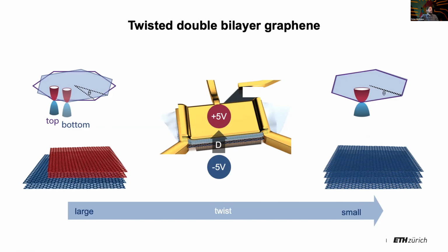I get delta R2 for the outer one, which is here. And then I can see whether the total resistance here, if I tune one to spin up and the other to spin down, exceeds the sum of the 2. And indeed it does by roughly 40%. So that's at least in accordance with what we would expect from the picture that I've shown you before.